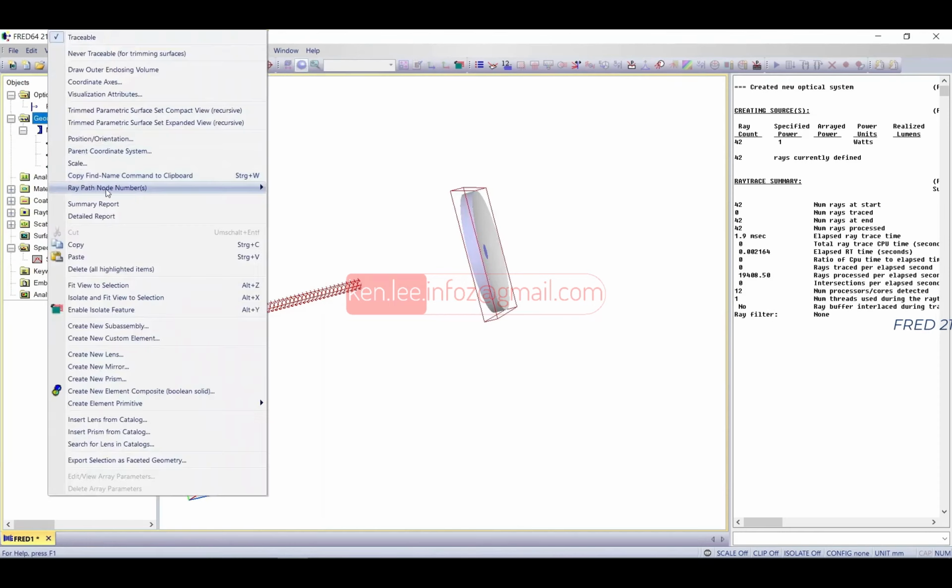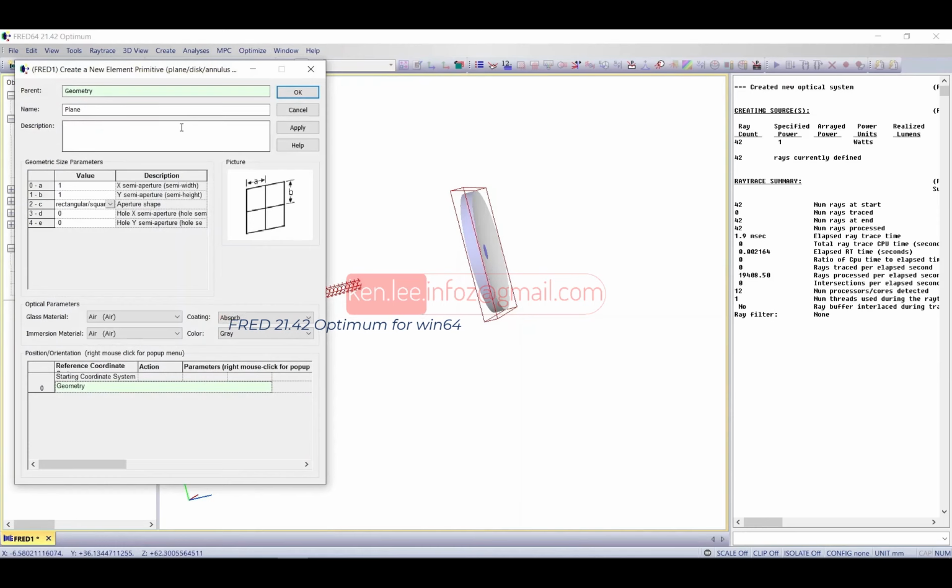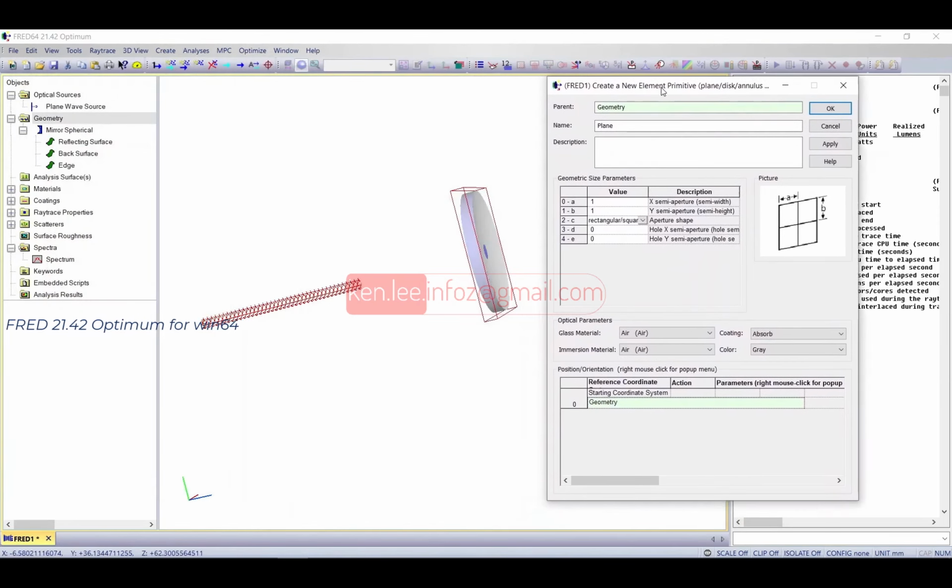and we wanted to do a grating, so I would say we create a primitive element, and this time we will use only a plane, like a simple surface. We don't need anything complicated. Could use a block and just make one of the surfaces a grating, but we will just use this diffraction grating. There it is. The source was something like 2 millimeters, so we can make this 2.5 times 2.5 rectangular. That's quite usual for gratings.